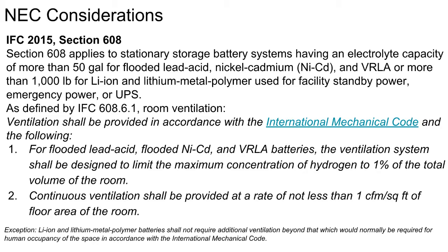And then a sealed battery is even more expensive and has an even shorter life. By the time you get into sealed batteries, either you're just trying to go for the lowest budget possible and have a small battery, at which point you're doing a sealed lead acid, or it's not a bad idea if you're looking at sealed lead acid to go ahead and consider springing for the lithium-ion technology.